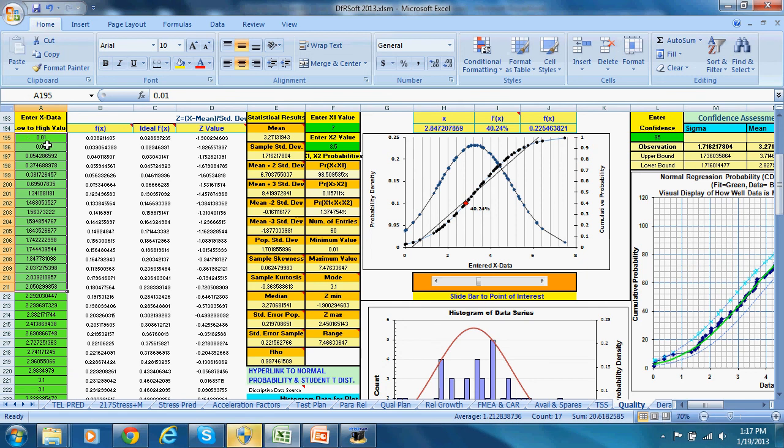We put in the values of our resistance; we measure, say, the 30 devices we're going to put on life test, and we measure the resistances, say 5 ohms, 4 ohms, 3.2 ohms, 4.8 ohms. Those might be the resistances at room temperature, and we put those in the squares here. Then we look at our graph.